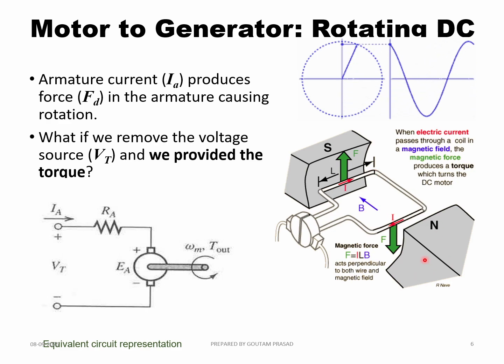In fact, suppose we are not feeding this coil with the DC power, and instead we are rotating this conductor with the help of a prime mover, eliminating the DC power. Then what will happen? If you rotate this conductor in the magnetic field B, because it is cutting the fluxes, according to Faraday's law of electromagnetic induction, it will induce power.